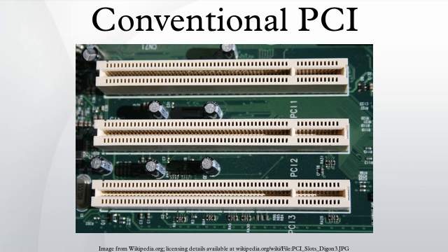The PCI specification also provides options for 3.3V signaling, 64-bit bus width, and 66 MHz clocking, but these are not commonly encountered outside of PCI-X support on server motherboards.